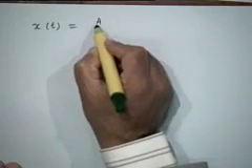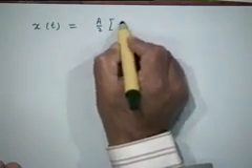So obviously the SSB signal had that representation. The VSB signal also will have that representation. The only things that will change are the actual values of x_I and x_Q, the actual nature of the in-phase and quadrature phase components. So we will certainly be able to see that this signal that we have generated will have this form.